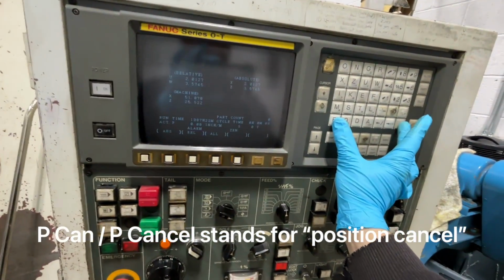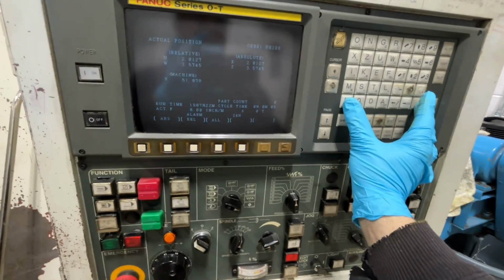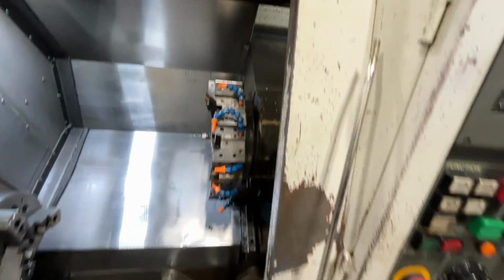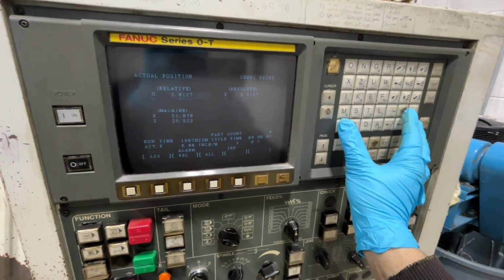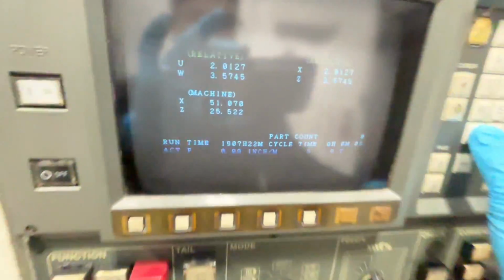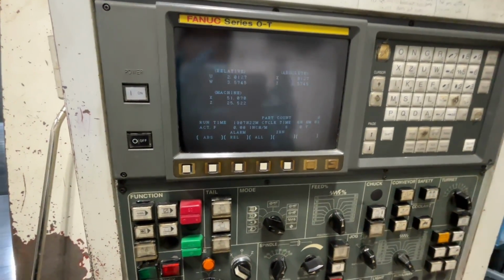And it's gonna tell the machine that you have no home position anymore. So it's gonna just keep going until the proximity sensor can fully do its thing, and then the home position will reset and the machine 0 will be correct. So I'm gonna try to set my phone up so I can demonstrate this.